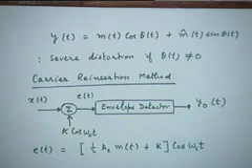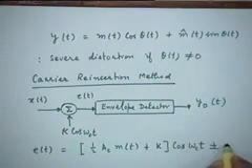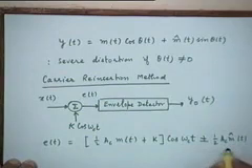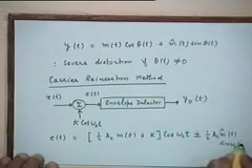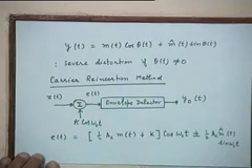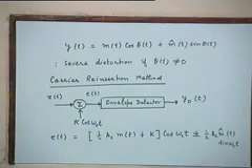And what is the quadrature phase part? Well, depending on whether it is lower sideband or upper sideband, we'll have half Ac m hat(t) into sine omega ct. One of the very nice advantages of a quadrature representation of this kind, remember we have discussed this quadrature representation for arbitrary narrowband signals, and it is interesting to see that the various kinds of AM signals that we have discussed each fall into this representation, right?